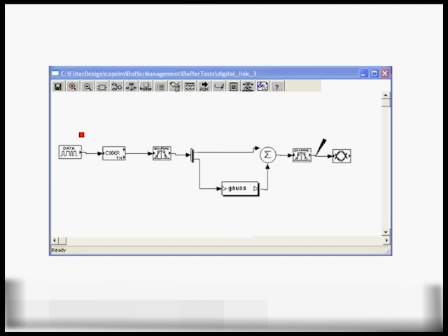But in general, the source block is scheduled first to be executed, followed by blocks that process the samples from the source block. Now, it is very important to understand, in terms of the simulation kernel using Capsim, that a source block is only run once, and then all the other blocks are run until there is no more activity on their buffers, and then the source block is visited again and it generates samples. This is done in order to control the growth of the buffers in the Capsim simulation.